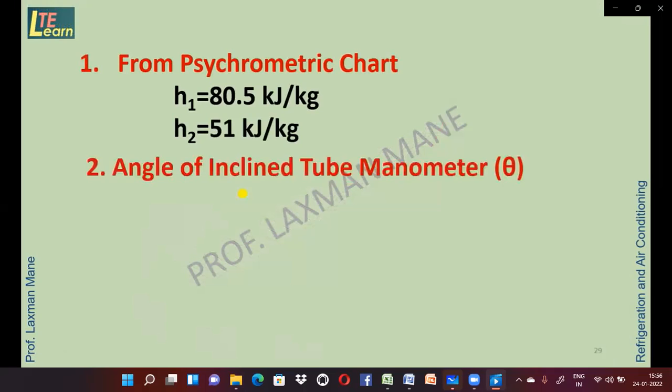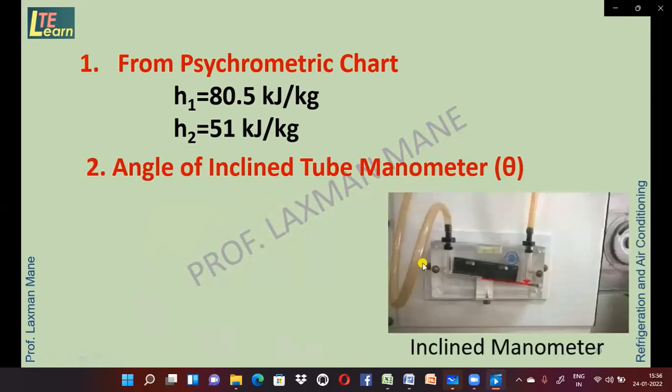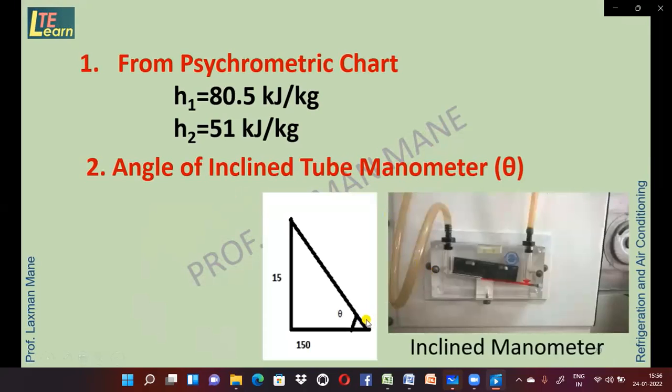Angle of inclined tube manometer. To find this angle, we need these distances. So this is a triangle. 150 mm is the distance between these two vertical limbs, and these are the bottom points. 15 mm is the distance between these two points. Let us take the tan ratio, that means tan theta is equal to 15 divided by 150. So angle theta is equal to 5.71 degree.